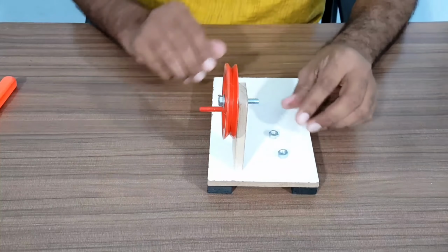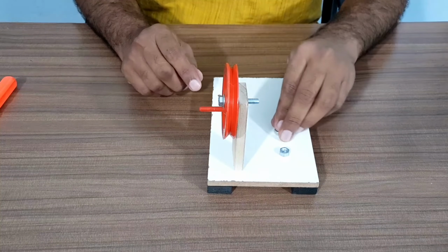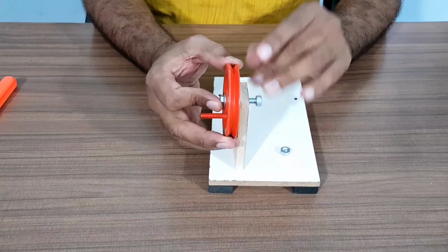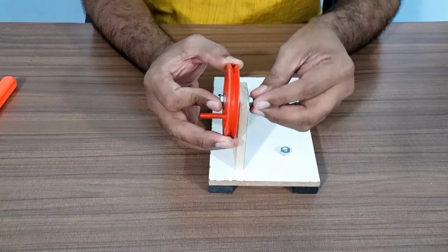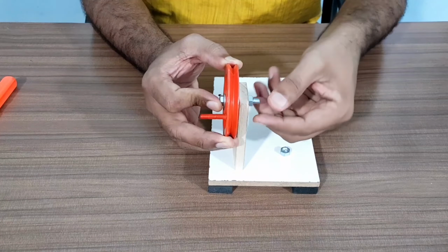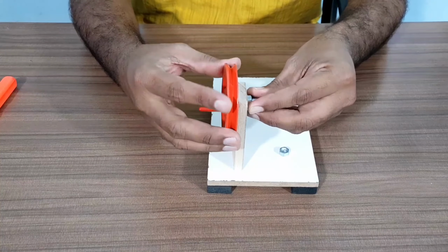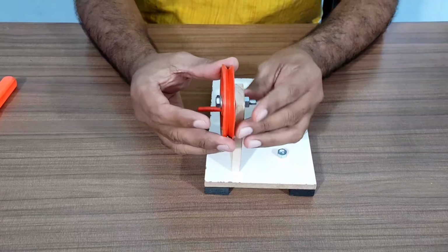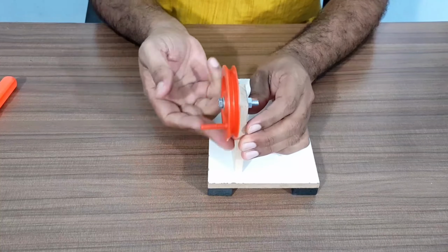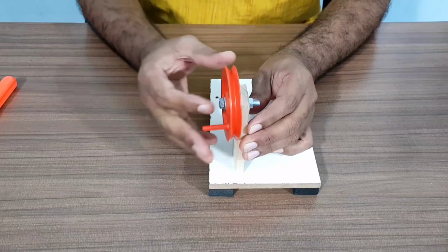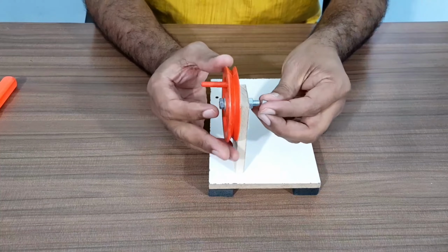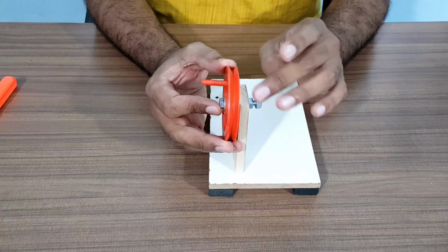And now using these two nuts, actually we have to make a lock nut assembly. I will tell you how to make a lock nut. When you tighten it, if you go on tightening it, this will be fixed. So don't tighten this nut too much. Make sure that this is moving freely. When this is moving freely, then take another nut, put it inside.